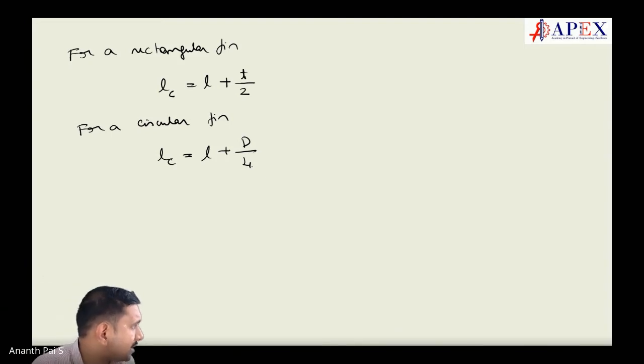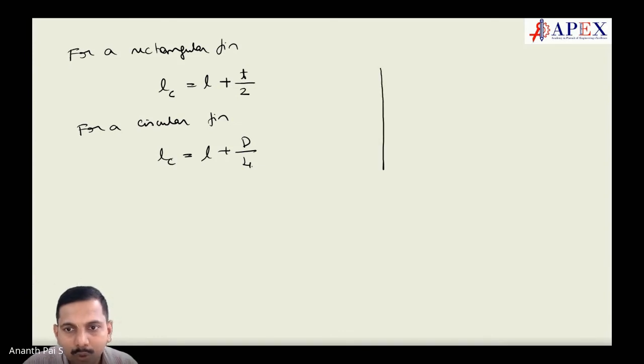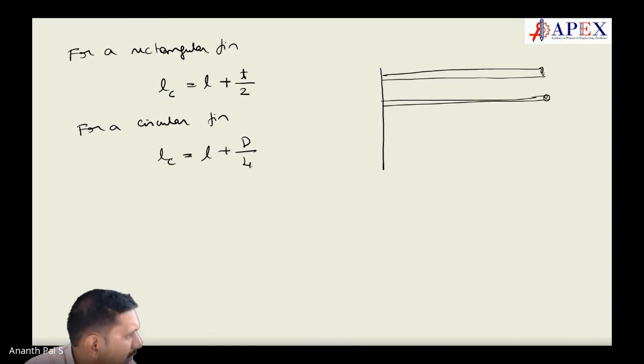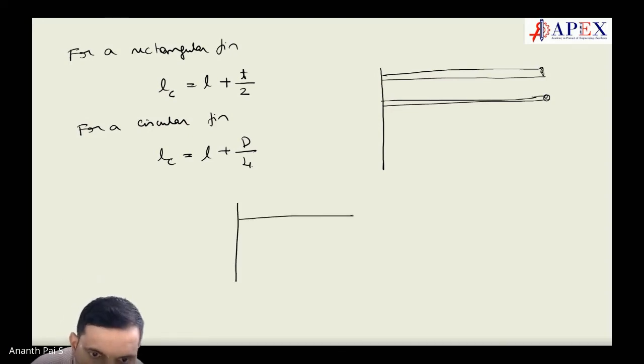Now I'll tell you the cases where these are used. In case you have a long tube, say in IC engines, instead of that I use a very long tube. Sometimes we use it, and it is open to the atmosphere. Very long but thin. This kind of fin is used. Then this can be considered as infinitely long. Generally, in case of an L by D ratio of 8 or more, we consider it as a long fin only.